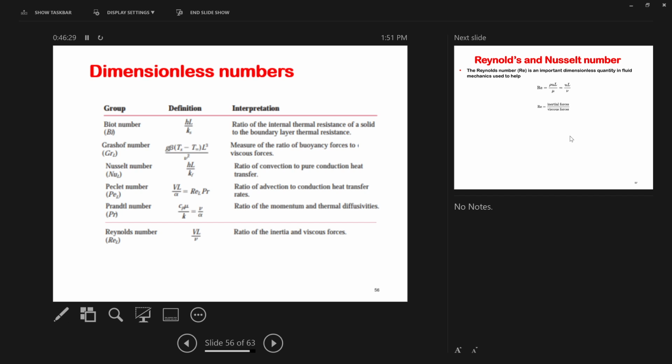Does that make sense? So in order for your lump capacitance assumption to be true, your Biot number must be very small. That's the idea. And we usually use the cutoff limit of 0.01. Some people use 0.1, 0.01. But the point is it has to be very small.